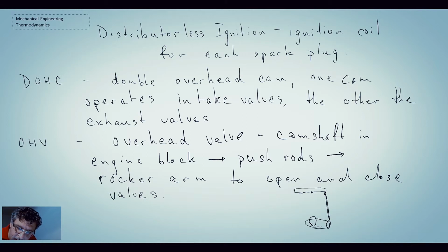Like I said, it's a teeter-totter. And then it would be connected to your valve, which is over here. And the valve itself would have this spring on it on the top. So normally it would be in the closed position. And as this moves up, this is going to move down. And given that it has a lever advantage, it could then push and open the valve, or it would close the valve. So that's the mechanism by which the overhead valve would work.